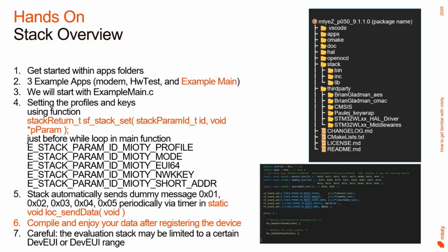A little overview of the stack, and I'm picking up here again what Mario already showed. It's a really flat folder structure, and what we'll need to get started is really simple, just the apps. The stack itself we actually never need to touch. In third party, you will find the ST drivers, no need to touch these either. You might want to add some drivers later to the hardware abstraction layer, but to start, you will really only need the apps folder.